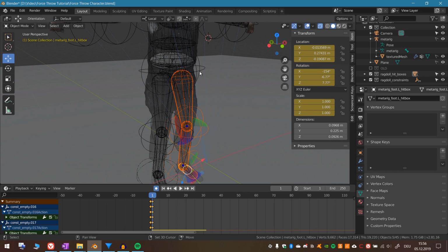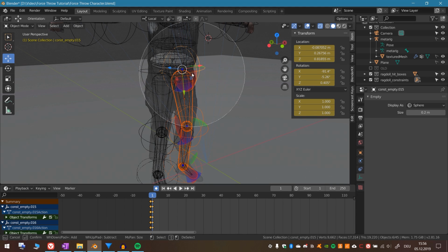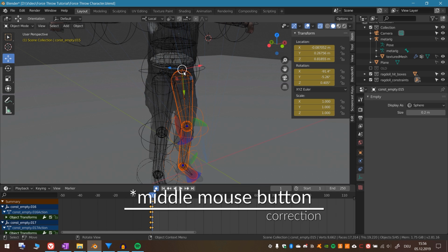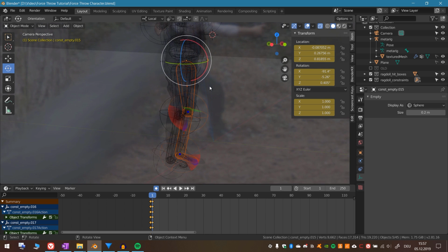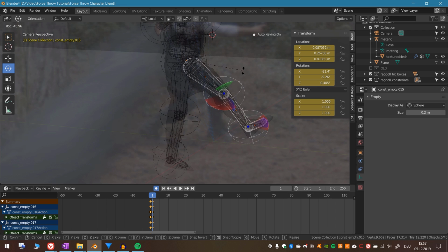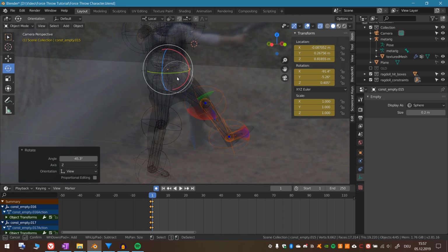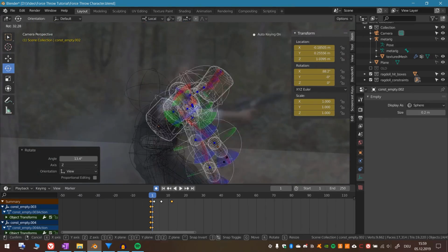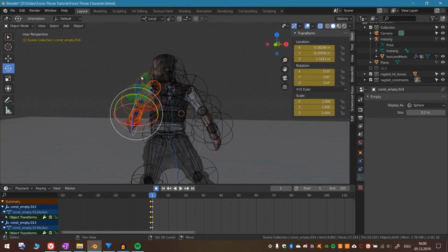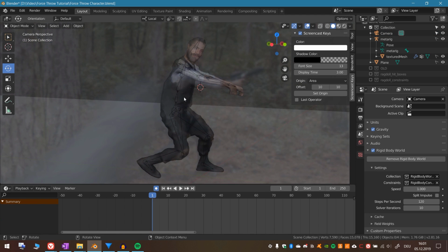At last you want to select the first constraint of the leg, and then with C and left mouse button deselect it again. That way you get the gizmo at that position. And when we change to rotation mode, go back to the camera view, we can rotate the whole leg from that position. Repeat this for every joint. The positioning doesn't have to be perfect in this shot since he's flying away pretty fast. But when you're finished, deactivate the auto keyframe button and give it a play.